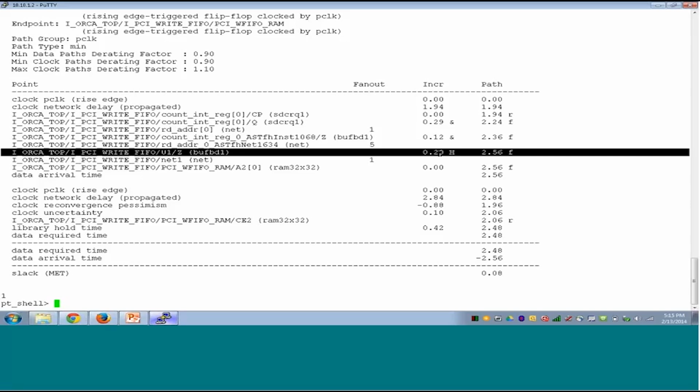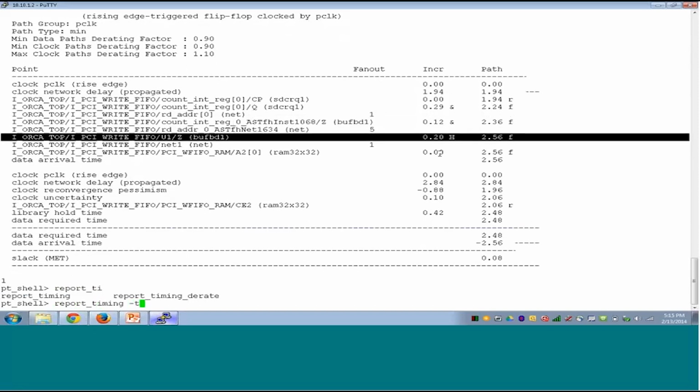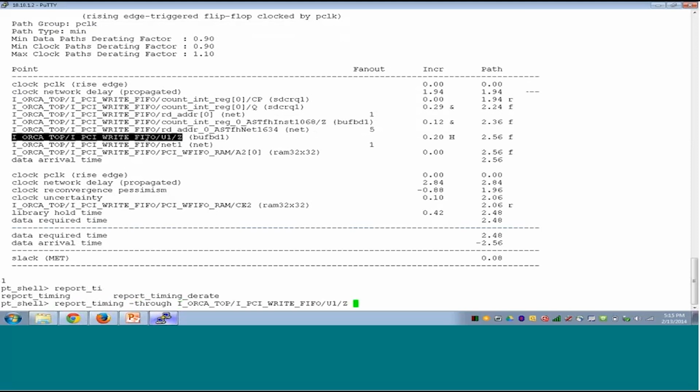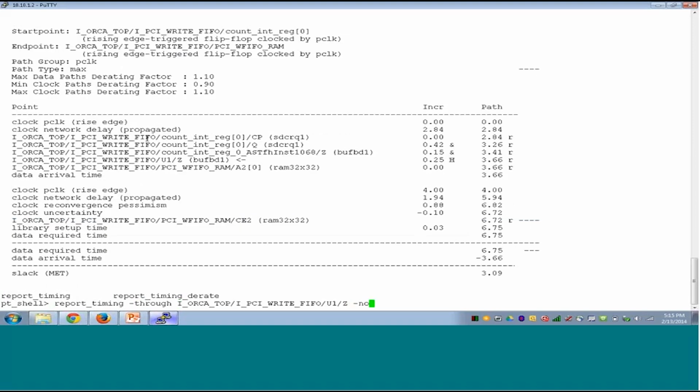So all such what if analysis you do, you can write out in an ECO file from PrimeTime. That ECO file you can give to the backend engineer and get the ECO implemented and legalized, right? So we could see again the setup slack through this particular cell that we have added. So fine, setup slack is also fine.